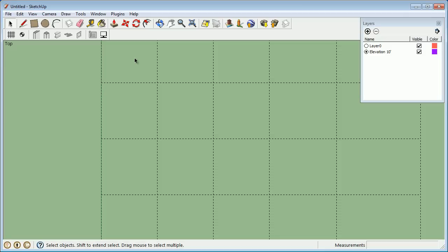In this tutorial, we will learn a few tricks that will help us to maximize the utility of the SketchUpBIM toolbar. Let's start with units. SketchUpBIM supports both metric and imperial units. If units are not explicitly entered, SketchUpBIM tools use the default SketchUp model units.